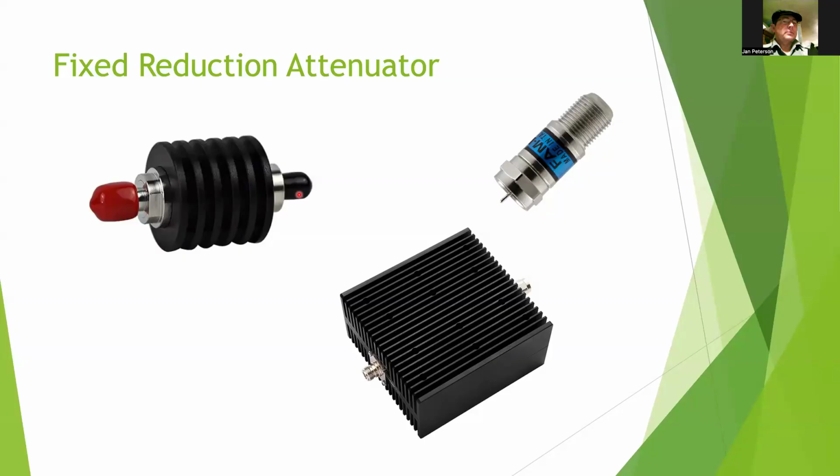And why would I want to use that? Well, I would use that if I'm testing like the power of my radio, but I don't want to be transmitting all over the place with it. I would run my radio into my power meter and then coming out of the power meter, I'd go into a dummy load. And then that dummy load is going to dissipate all of the power of my signal, almost all of it. There will be some leakage, right? But probably 99.99% of my signal would get turned into heat. And the dummy load will handle that.